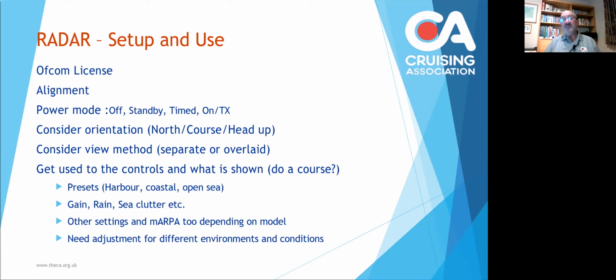And the thing is, all of these need a little bit of adjustment for different environments and conditions, and maybe even what you're doing. When I'm using radar, quite often I will be changing the gain and changing the range that it's set to from minute to minute, so that I have a quick look over a large area, and then I will look more closely close up.